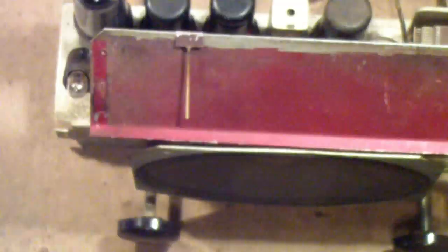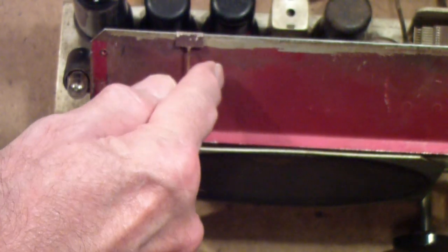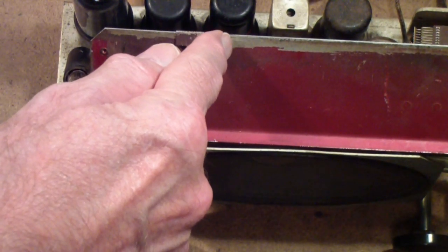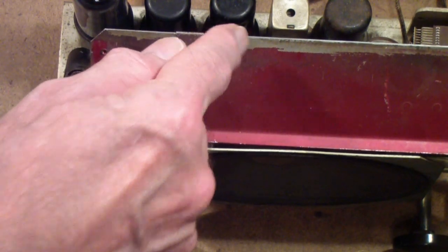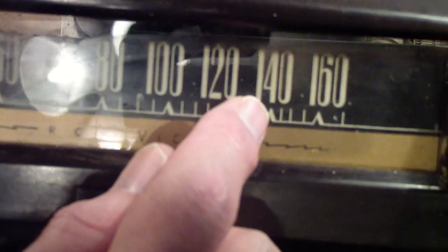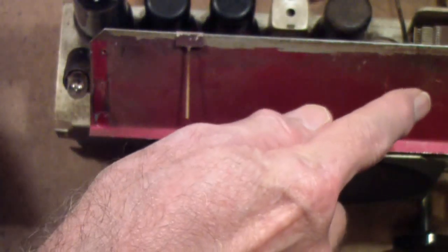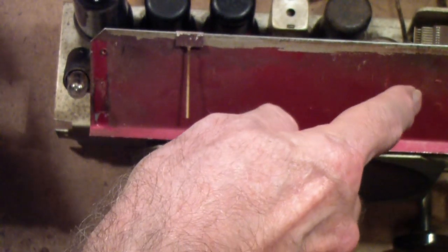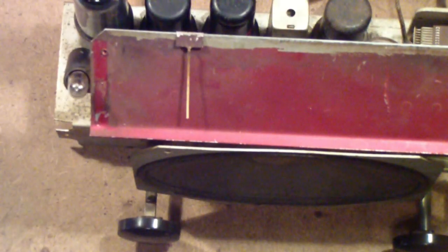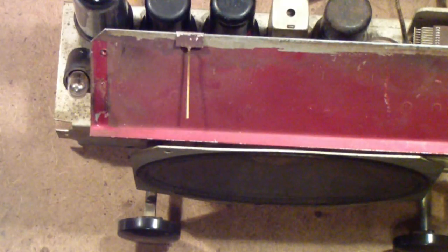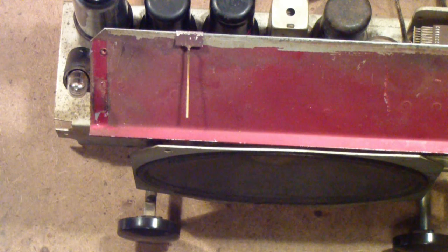Then don't move the dial, take it out of the case and mark on here where that is, so that you can locate it again pretty accurately. Similarly, you should pick a place near the top, maybe 1400, as another dial mark, and mark that on the dial up here where it matches. Then, when you're doing the alignment with the unit out of the case like this, you'll be able to find those points easily.